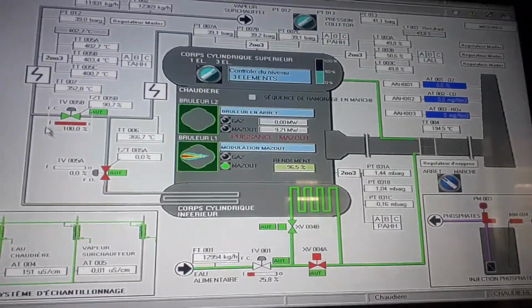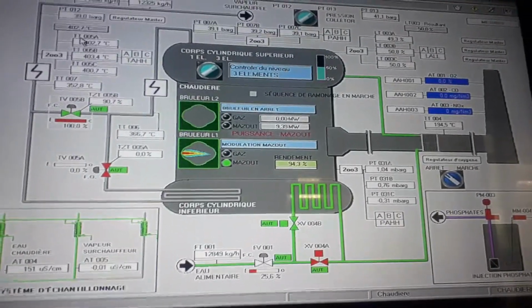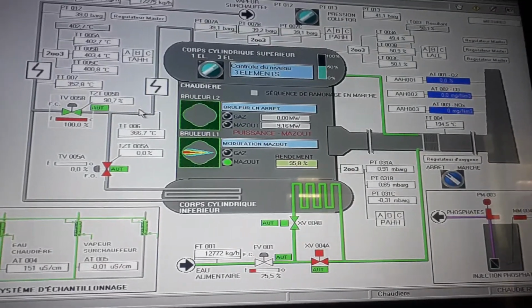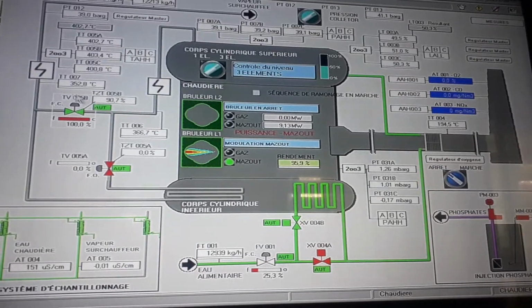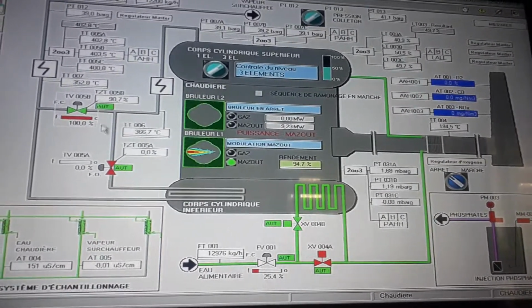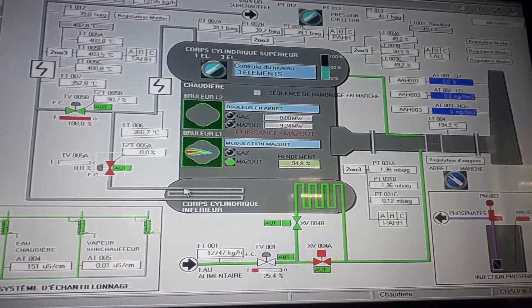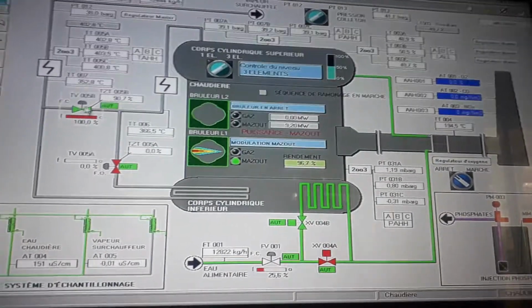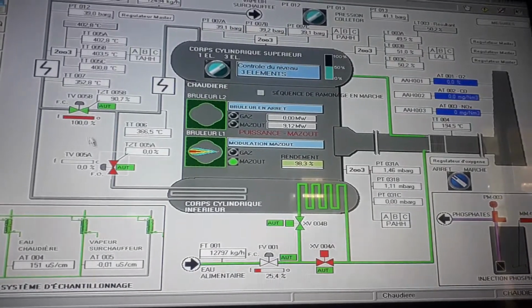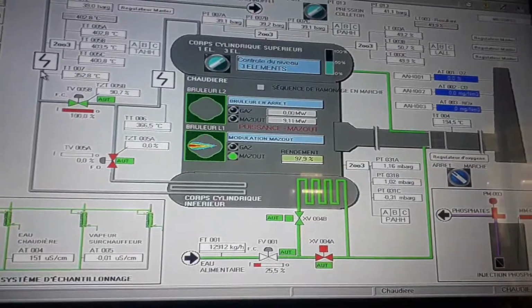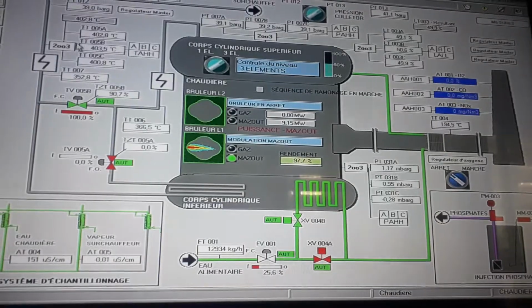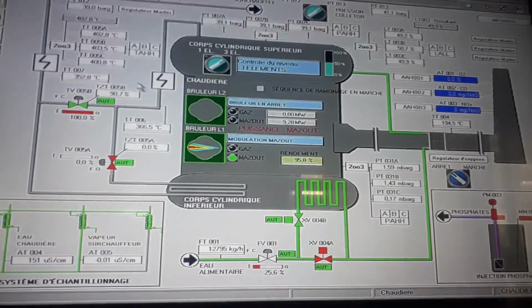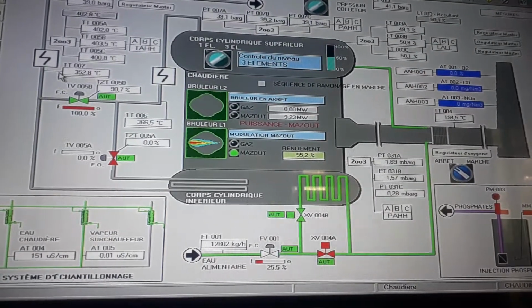Of course, we have here two valves to regulate the temperature. To get a temperature here of 400 degrees C, we have to regulate it. An amount of the vapor goes from this valve to the second superheater, and another amount goes to the superheater to regulate the temperature. The regulation of these two valves depends on the temperature in the second superheater. After going out from the second superheater, we get a temperature of 400 degrees C and a pressure of 41 bar.